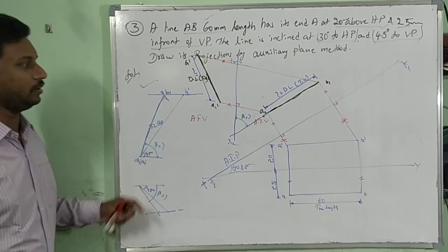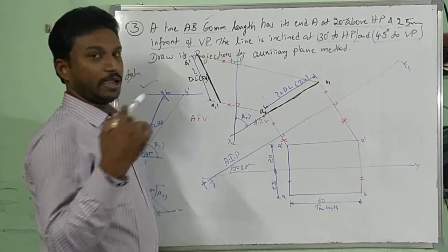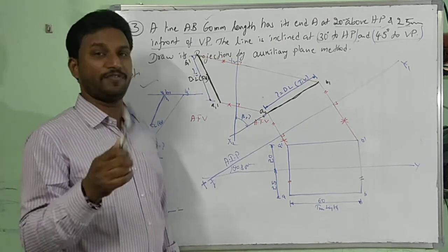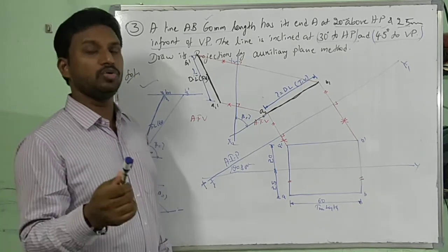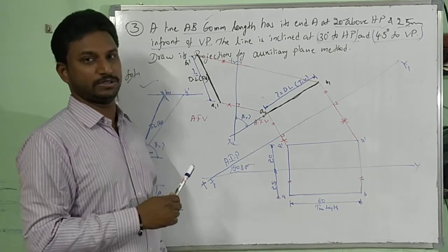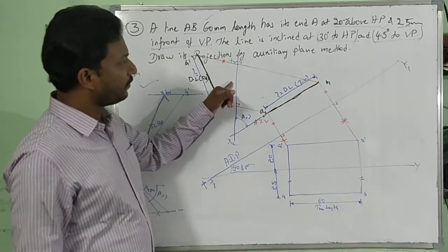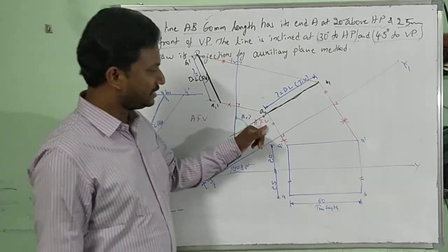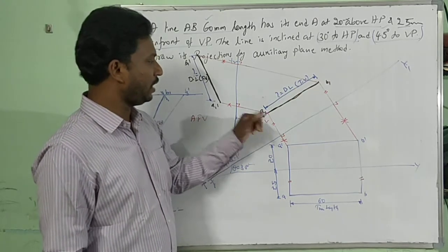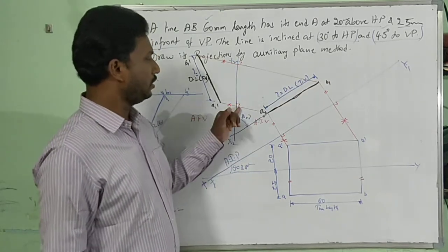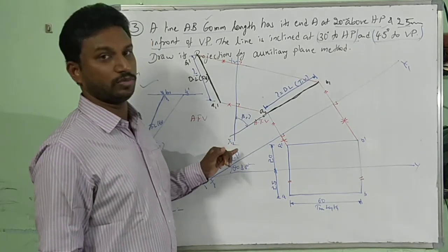That depends upon the figure. Once it is drawn, from the adjacent view you are supposed to draw the perpendicular lines, right? For the new reference line x2 y2, the adjacent view is the auxiliary top view. From those points A1 B1, I have to draw lines perpendicular to x2 y2, 90 degrees.